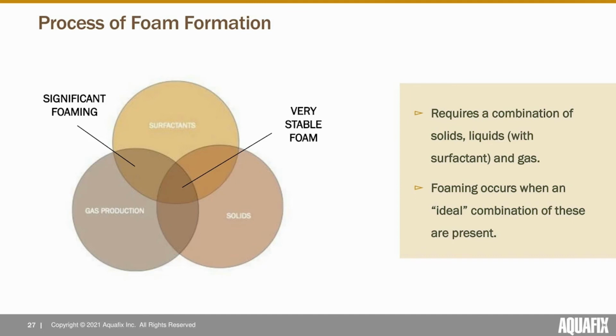A lot of the time, foaming is the worst immediately after you've had digester souring and you begin to correct the pH, because you'll have a lot of volatile acids accumulated, and then you'll begin generating methane and carbon dioxide once the methanogens start working again, and then you get a big foam. And to make matters worse, a lot of the time, if you're supplementing something like sodium bicarbonate, you might have some foaming occurring as a chemical reaction with the acetic acid present in the digester.